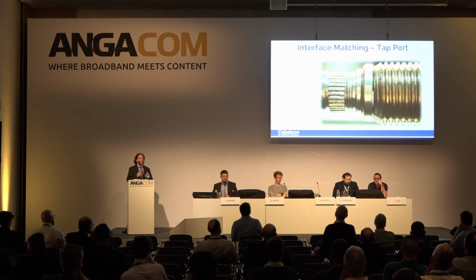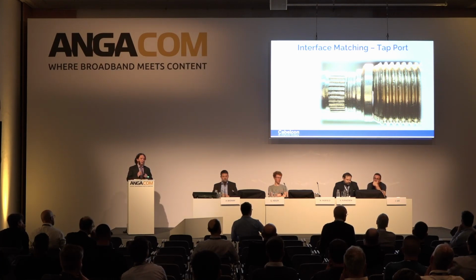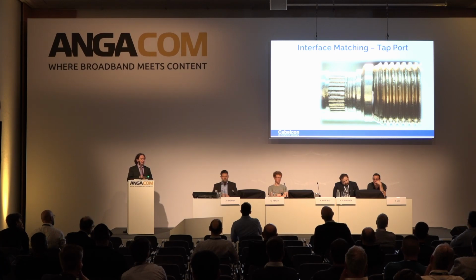So I've got a few slides of just looking at how a standard port will go onto a connector interface. This is a stripped-back view of the connector, so the nut's removed, and this is purely the center of the connector looking on various ports. On the left-hand side is the connector itself, and the right-hand side is the port. Actually, there's a little white glint in the middle in that interface, and that's basically where the RF isn't sealing. And you've got a potential source of ingress. So even though the connector could be torqued up fully, there's still a gap in there that could leak RF.